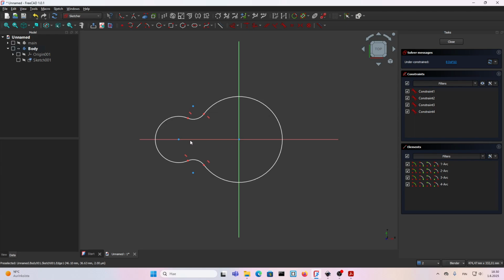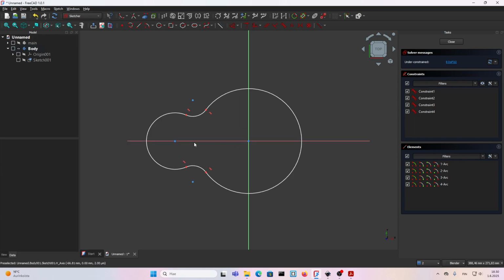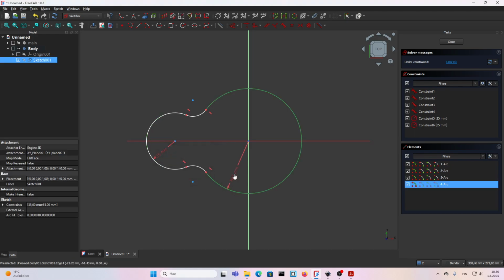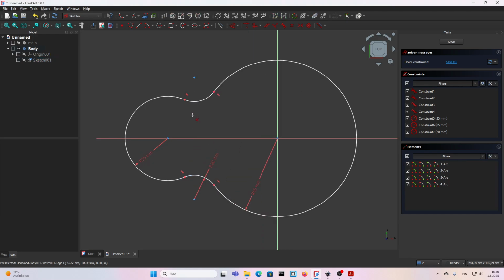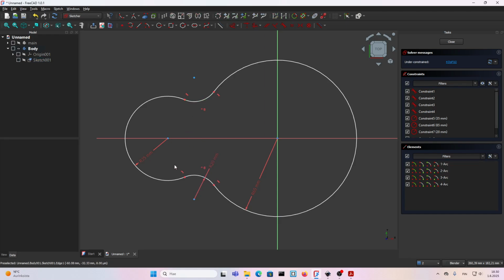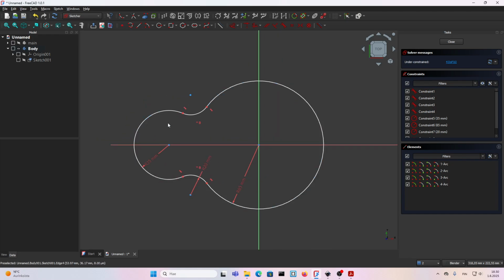See, we have it in here. Now we need to constrain it. D from the keyboard, start constraining like this. Let's constrain them all like this. One thing, keep attention on, when you constrain, keep your constraints on this side, because later we are going to trim this one, and I will tell you why.